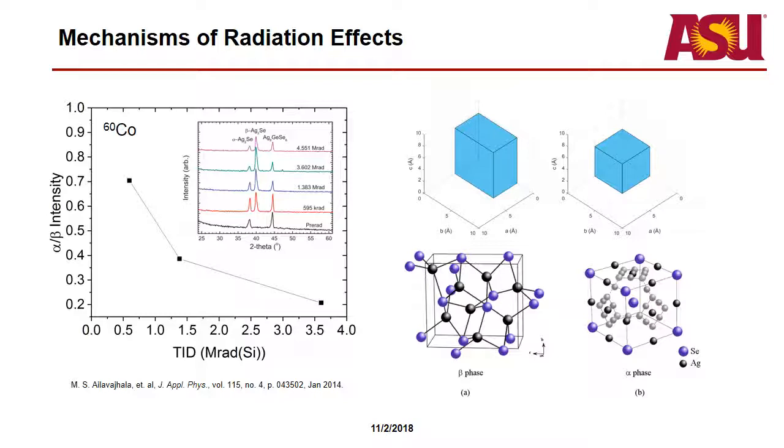And again, like I said, for IV tests, you're applying that bias for a really long time. So you're allowing sufficient time for those ions to migrate to the filament, especially at the lower doses of radiation. So in the cases of doing IV sweeps, it's not until a significant amount of dose that your device has been exposed to that you see those effects.